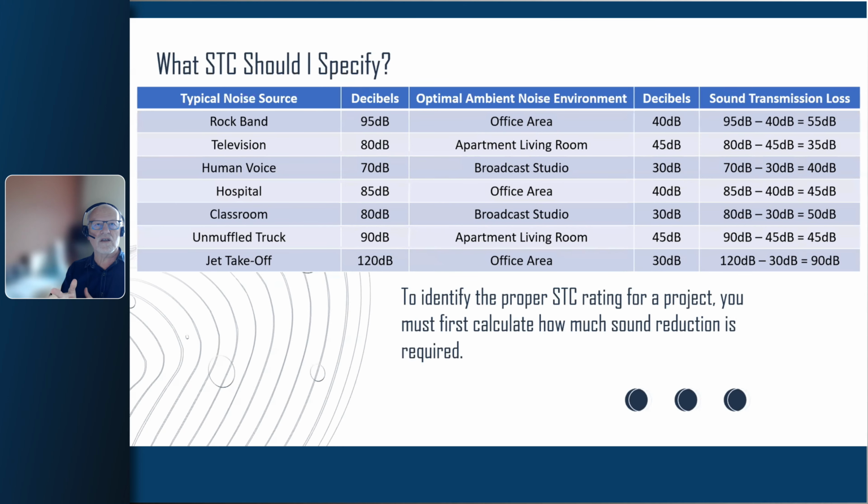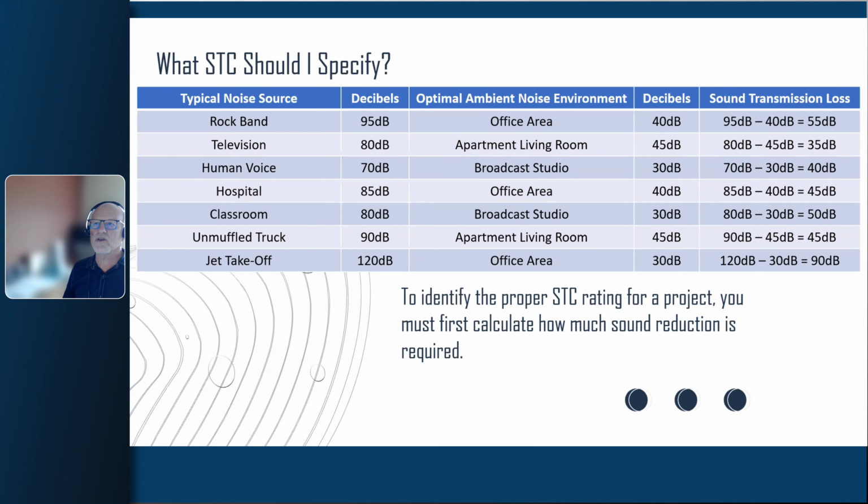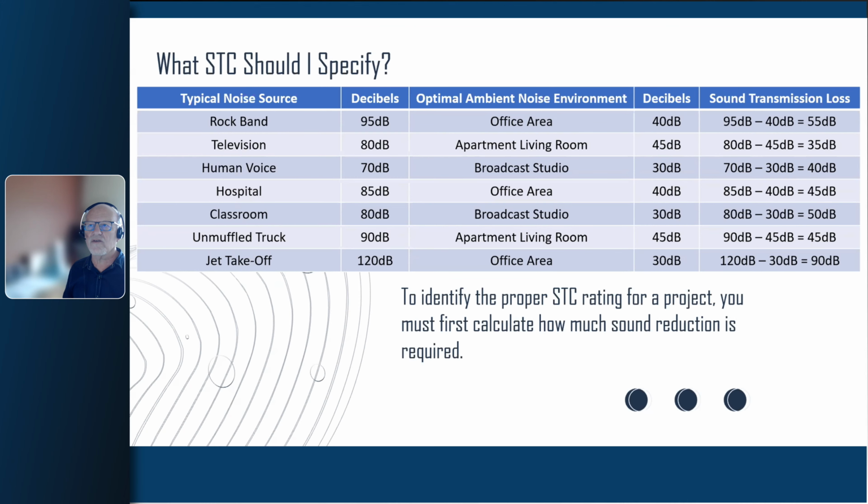And they were supposed to achieve, the spec was for STC 50. And there was a great deal of concern that noise would get into the exhibition halls from the stairwells, that people would be having conversations or other rooms around the exhibition hall. So part of our contract was to do field testing.